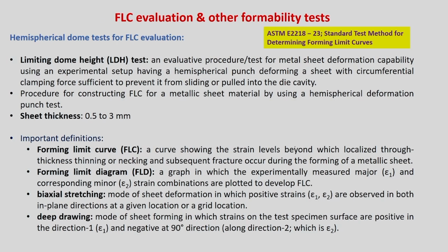That's why the topic today is FLC evaluation, forming limit curve evaluation, and other formability tests. Formability is nothing but the ability of the sheet material to be converted into a particular shape without any instability, without any necking, without fracture.